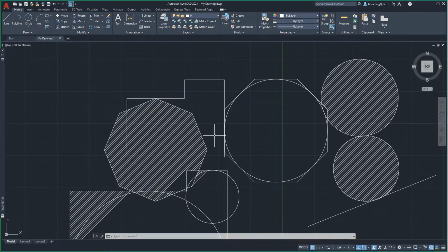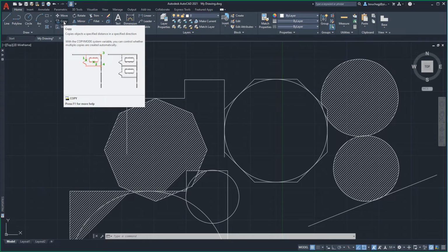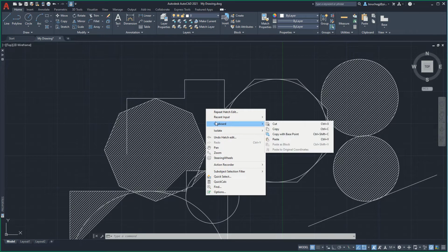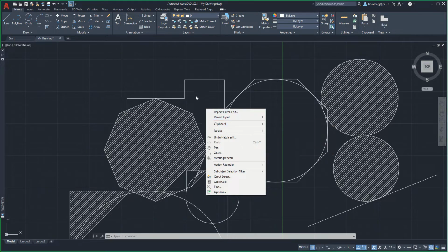In the Home tab Modify panel, below the Move command, is the Copy Selection command. This functions differently than the typical copy and paste command using Control-C and Control-V keystrokes, or using the copy and paste commands found in the right-click clipboard flyout menu. When using the simple copy command, the items are copied to the machine's random access memory. When pasting the items, they are held to the cursor by a lower left-hand corner location and have no connection to the location of the cursor when the copy command is invoked.